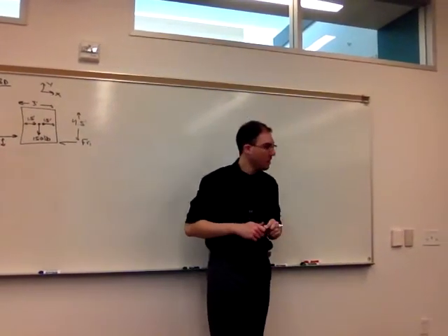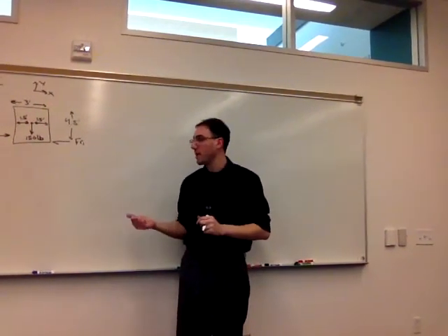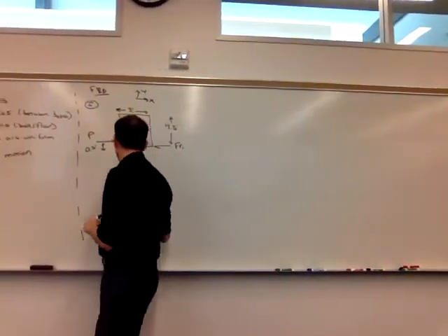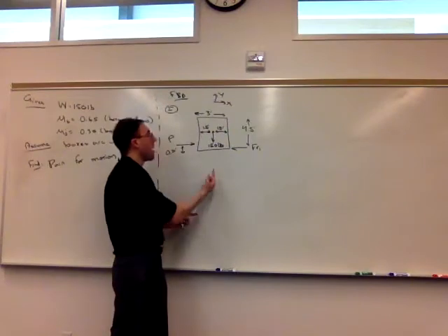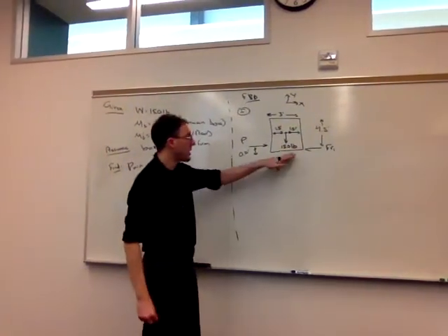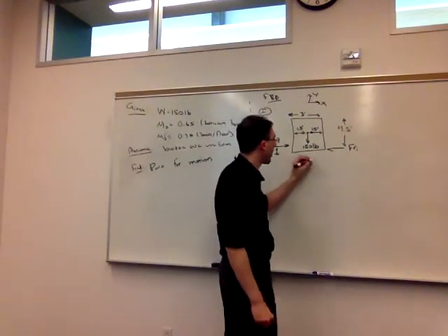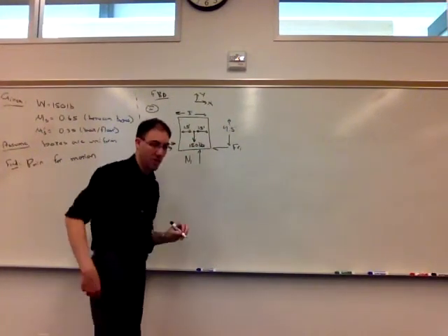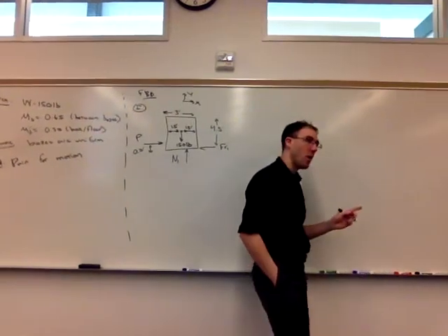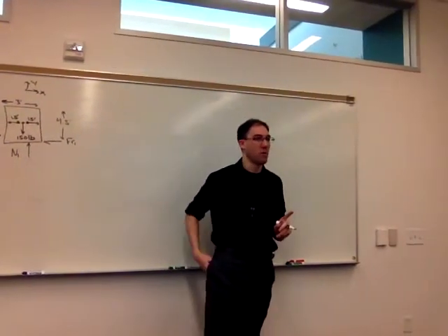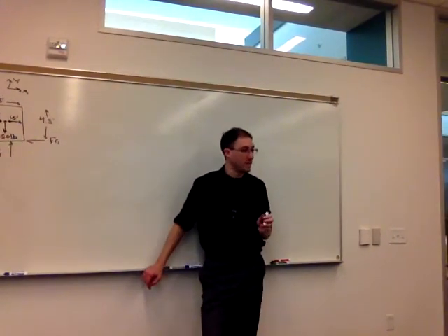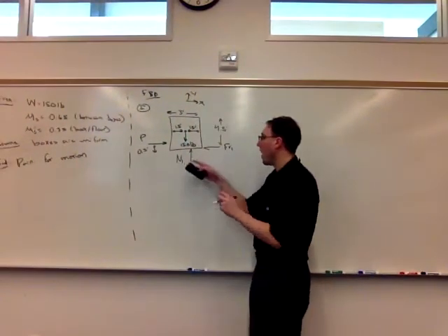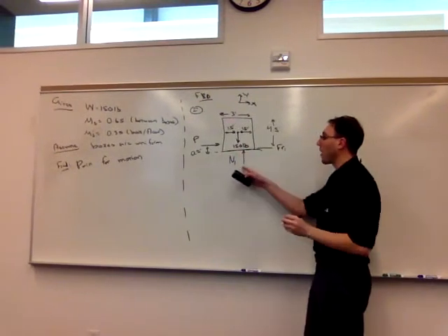Is there a normal force too? Right, anytime there's a friction force, at least for Coulomb friction, there has to be a normal force. So the normal force is the force from the bottom box pushing up on the top box. So we know the surface at which it acts. We know that normal forces always act, as the name implies, normal to the surface. But what do we not know about that force? Where it's located. Right, we don't know where it is. We know that it's somewhere on this axis, but we don't know where we can put this.